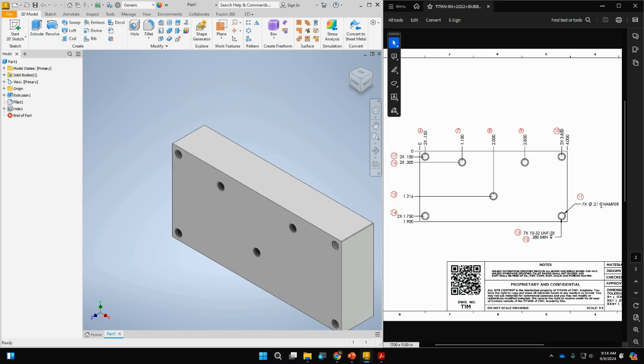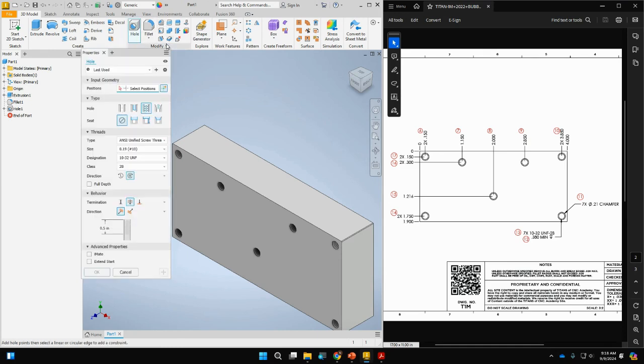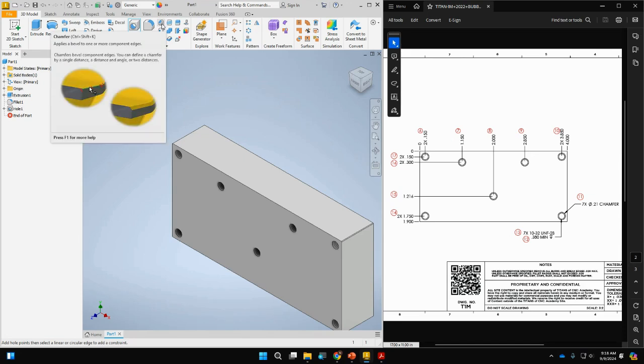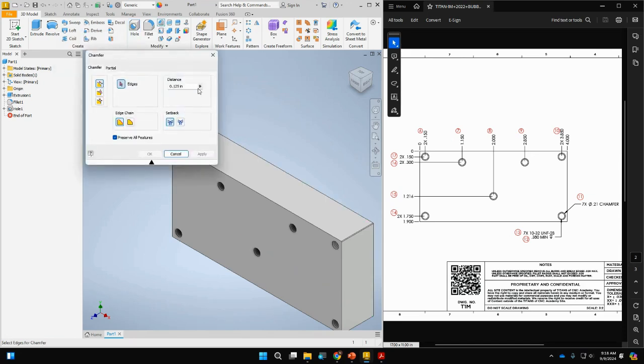So now I'm going to add a 0.21 diameter chamfer. All right. So this is a little bit goofy here. I have in my fillet menu, right, I've got hole and all that stuff, and then I've got some smaller ones here, which depending on how zoomed in you are, you may be able to see. But this, my chamfer, is my angled, beveled edge. And if I go through and I make this 0.21, that's not going to work. All right, so that's not what I want here. So this is telling me it's a diameter 0.21 chamfer, which is a little bit goofy.